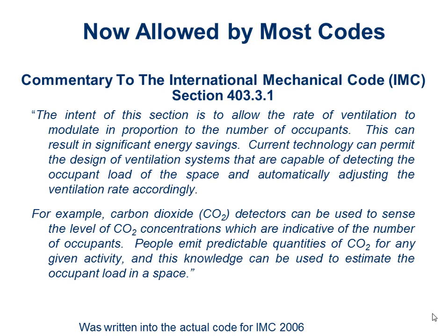So you're allowed to reduce the amount of outside air below the otherwise code prescribed minimum if you're going to measure the CO2 levels in the space and ventilate according to those. So that's really what we're talking about here today.